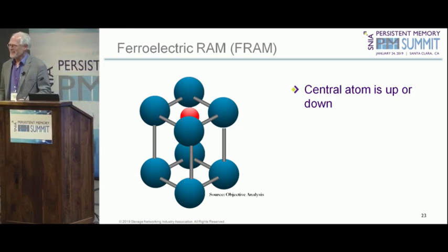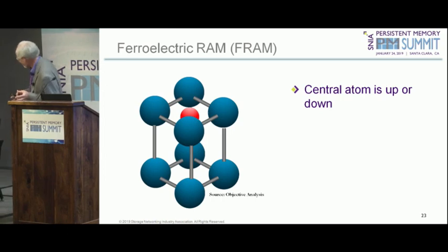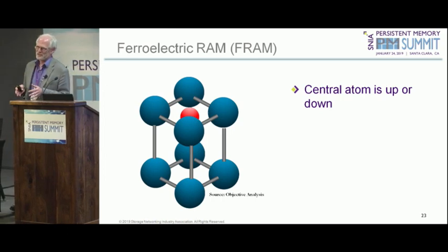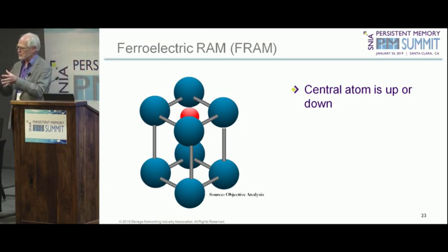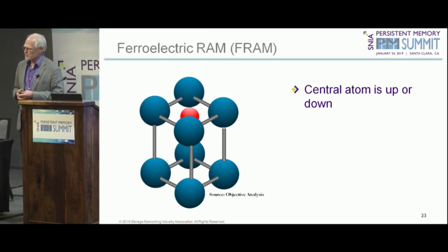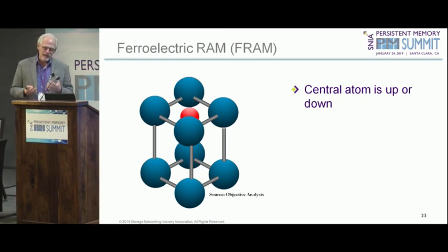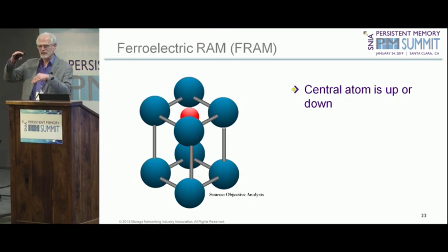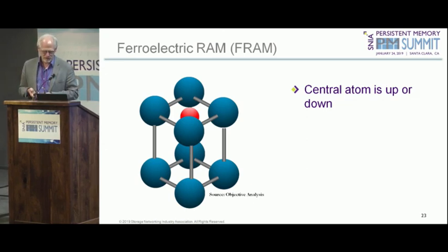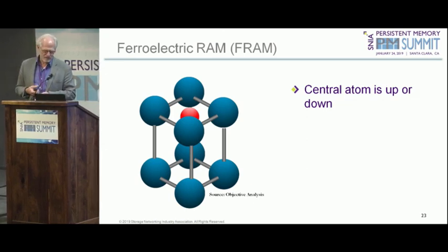Yeah, congratulations. So basically what happens here, thank you, Jim, is that there's an electrical polarization: you apply a voltage to this thing, and you can get a polarization of this material. It actually has hysteretic properties, kind of like a magnetic material, only it's this electric polarization that you're changing. So, like with magnetic materials, that hysteresis allows you to have two-state materials, and therefore, again, gives you a memory technology.